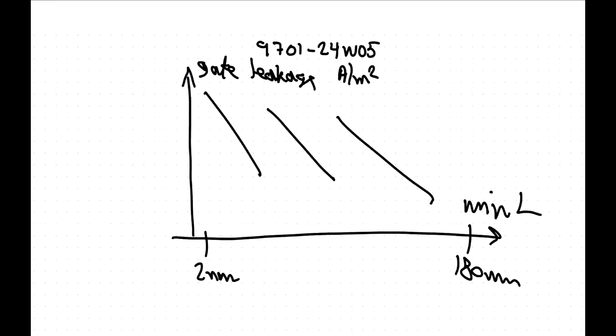So you make the oxide thinner, but then you've got gate leakage. Why don't we use a high-K dielectric for everything? Well, you don't do it up here because it is not necessary, and it's more expensive. Up to about 50 nanometers, you use silicon dioxide. Silicon dioxide is a really good material and it's very easy to manufacture. But at some point, the leakage becomes too large and it can't take the field, you can't get the channel control. Then you've got to change the gate dielectric to something more exotic.